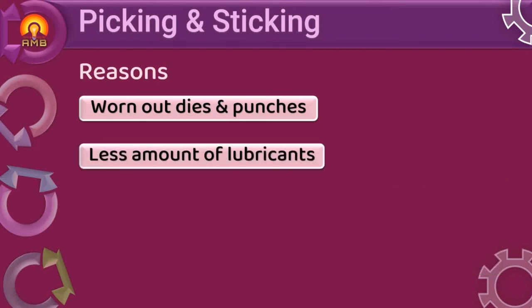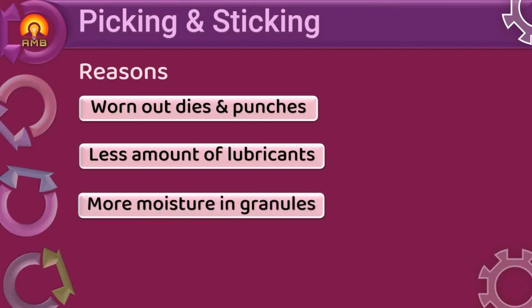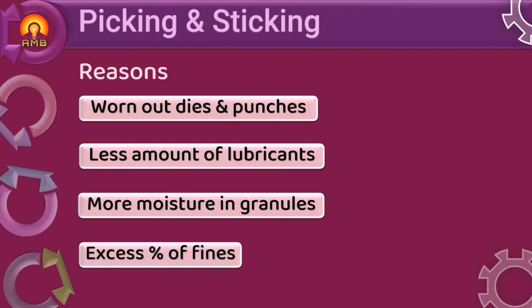granules is less, then picking and sticking also take place. Presence of more moisture in the granules may also lead to picking and sticking. Excess of powder or fines present in the granules also leads to picking and sticking.